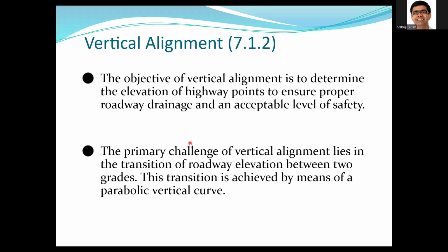Okay. The objective of vertical alignment is to determine the elevation of highway points to ensure proper roadway drainage and acceptable level of safety, right? So we want to make sure that you have proper drainage as well as safety. So we have twin objectives here.